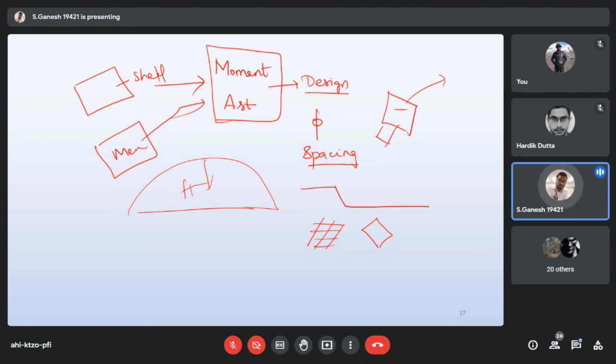How about openings in slabs? Can we design a slab using a plate, since we cannot make openings? Yes, that's what I showed. In plate, we can't do it. So make sure we don't have openings in plate elements. We need to create a surface and then create an opening. Plate will show an error, as I showed in the sample model right now. So it should be a surface element, not a plate element.